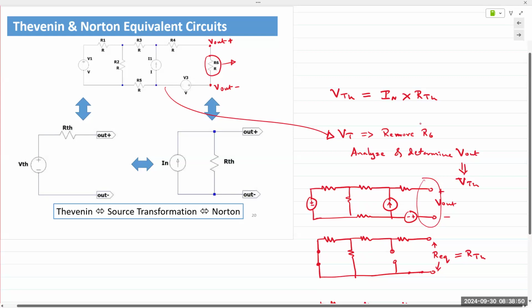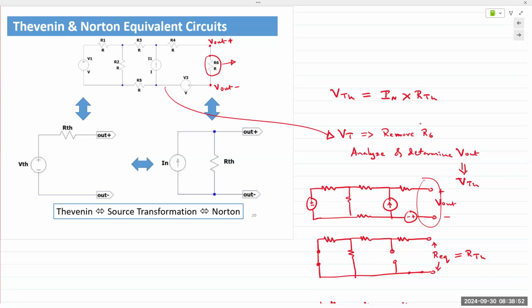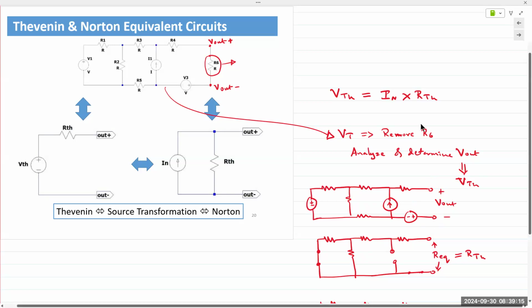And so from that point on, you set up the circuit to determine voltage, resistance, and the current. The voltage doesn't need any setup because once the component is removed, you have 2 open terminals. You simply measure or calculate, in this case, calculate the voltage at those terminals. That is the circuit that is required. So when I was saying don't overthink this, that's what I was trying to say. Does that make sense now, hopefully?